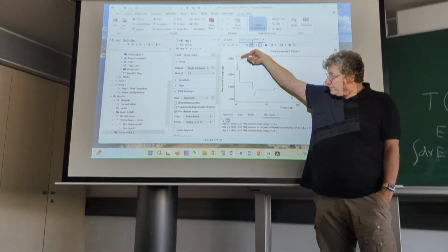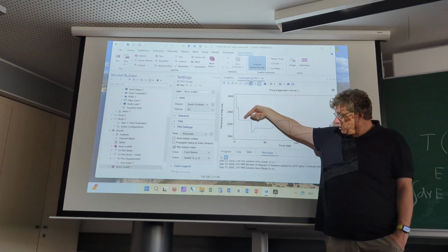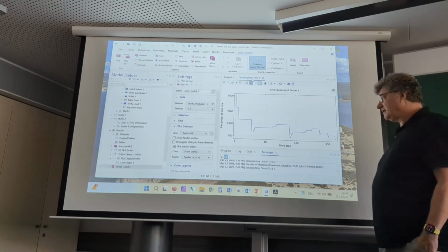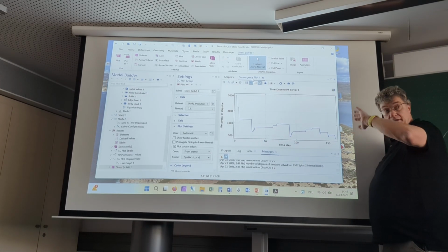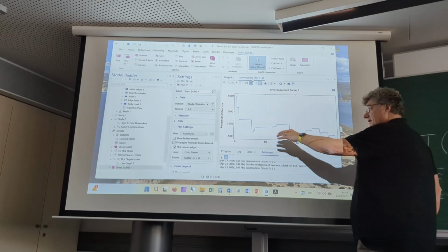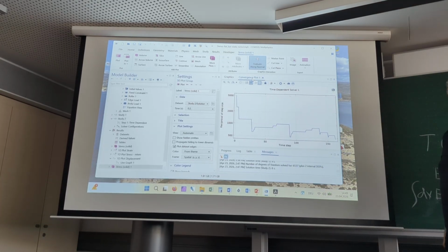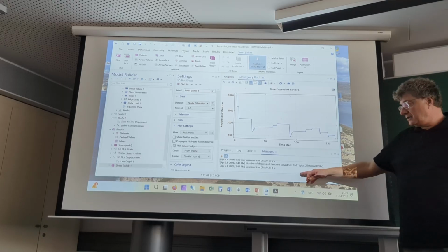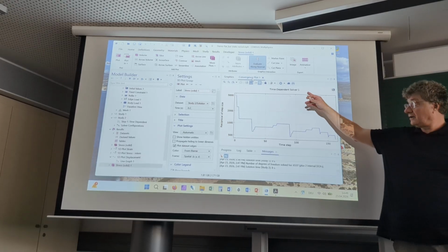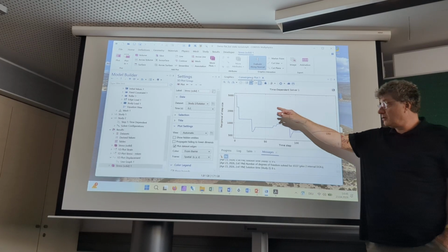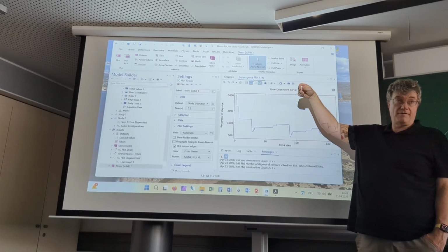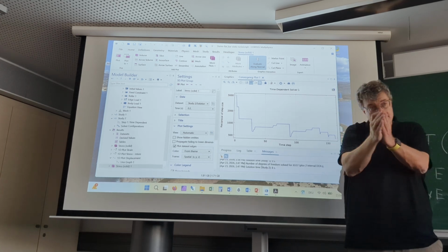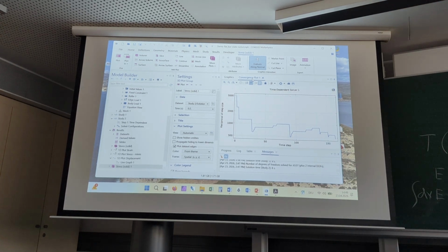It starts with a very fine time step and it gets larger, so it can proceed faster. And for some reason, I think that is somehow related to the periodicity of the simulation results. It adjusted accordingly. And if the simulation is not finishing, then maybe you find out something here in the convergence plot. It typically would run even higher. It gets a larger and larger number, meaning finer and finer steps, and still not possible to find the solution. Then you probably have to change something in the model.